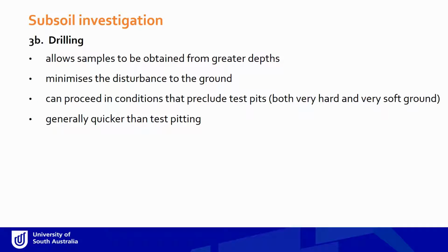On the pro and con side of it, drilling or boring allows samples to be obtained from much greater depth, as we have discussed. It minimizes disturbance to the ground. It's very important. Say we'll be digging a hole that is only, say, 100 mil in diameter, so the disturbance to the ground is very, very minimal.